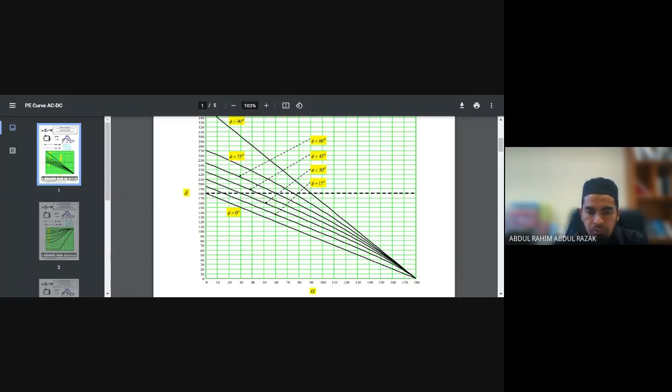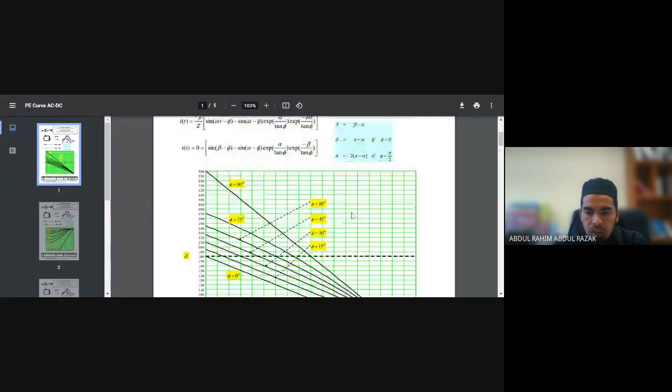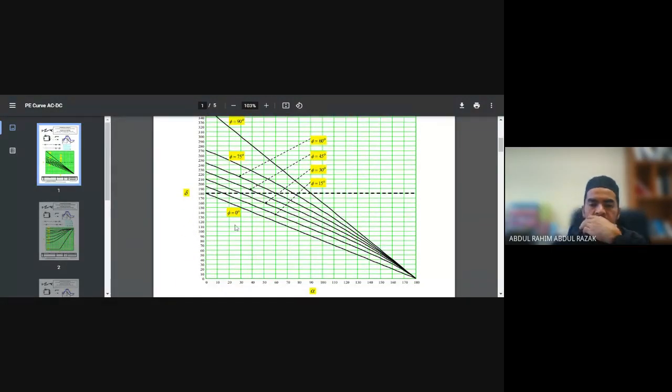Okay, for a diode, your alpha is 0. At a load angle, phi or theta, equal to 0, the element of L is the lowest, meaning you have the element of R. So if only R exists and you trigger at 0, your extinction angle is 180 degrees. Here the L is 0 and the remaining element is R, a pure resistive load.